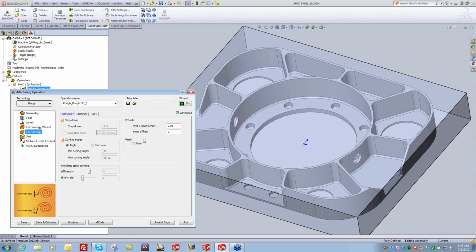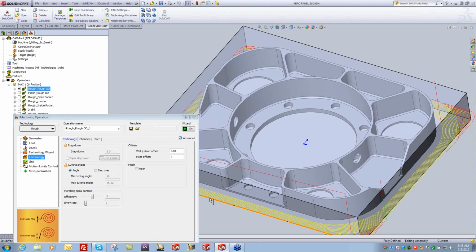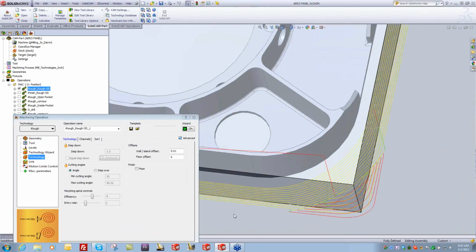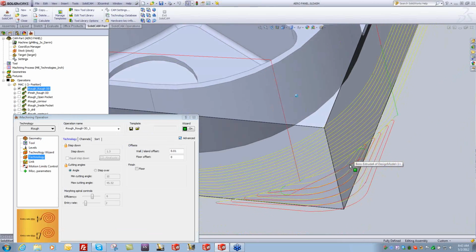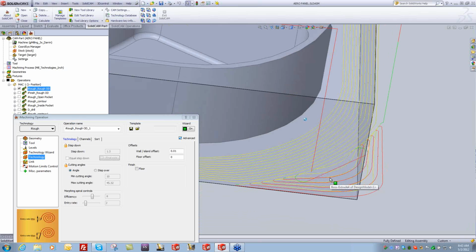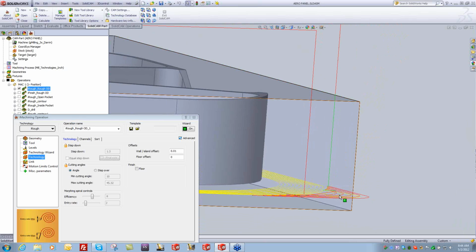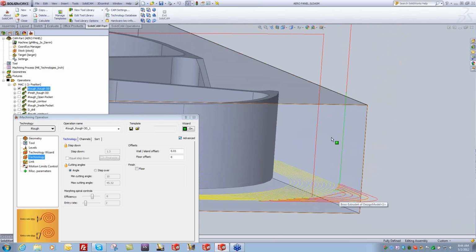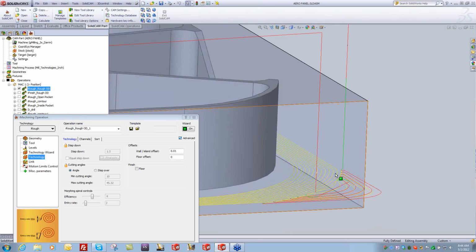Of course, you can finish the floor with iMachining. Personally, I recommend using a traditional toolpath for finishing, and here's why. If we turn on the toolpath, you'll notice that this is tool engagement. It's engagement controlled machining. So we're managing the engagement. But we're doing that because we're taking this full length of cut here. We're no longer cutting down in 1/4 inch increments or 800 thousandths or whatever, because we can. And that's why we can cut so much faster, because we're engaging only a certain amount of material.